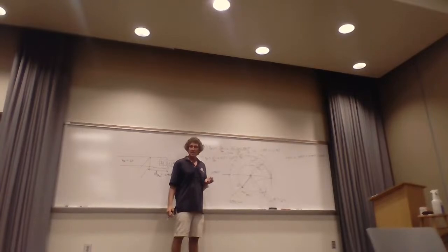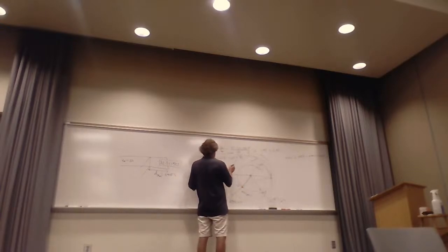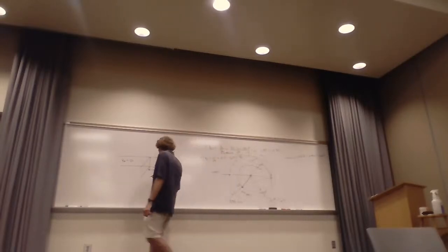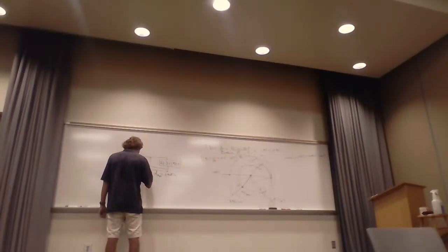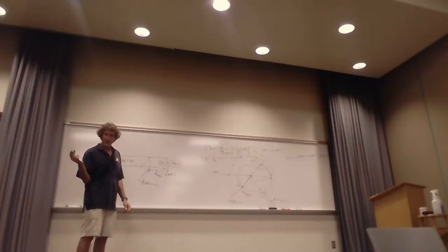A little to the right of that. j0.8 would be about 0.1 lambda? 0.108, roughly. Okay, so that means this is 0.108 lambda. This is one solution, and that would be the length of the stub right here. It would be D stub, 0.108 lambda. That's one solution, right?